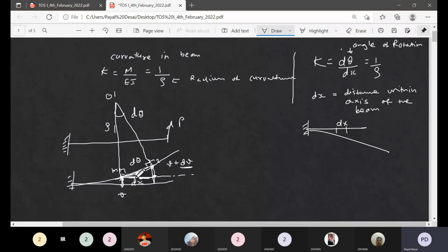So this can be d theta, right? If these two normals, and because this is the deflected shape and this is the horizontal, this angle can be, the slope that you define. You can write sin theta, or approximately we can write theta, cos theta approximately, but this theta will be this side over this side.